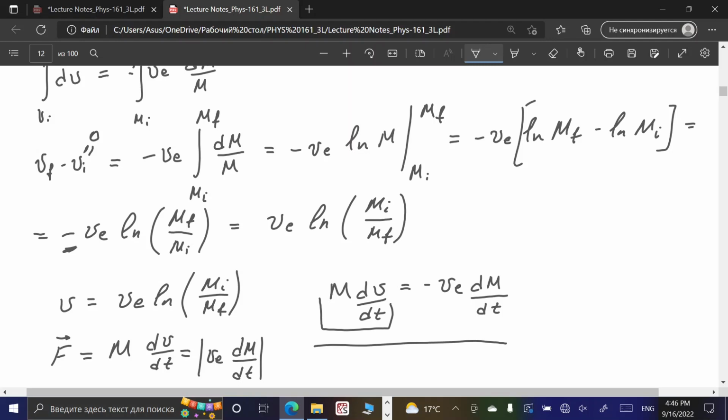Also, we introduced the propulsion motion principles and derived the general equation for velocity, which defines the velocity of the rocket as a function of the exhaust velocity of gases and the ratio between initial and final mass of the rocket. So eventually what we can claim for the propulsion force, we want very high exhaust velocity, meaning high temperatures, and a very high rate of burning, d capital M over dt, which shows how fast the mass of the rocket is reduced because of exhausted fuel and oxidizer.